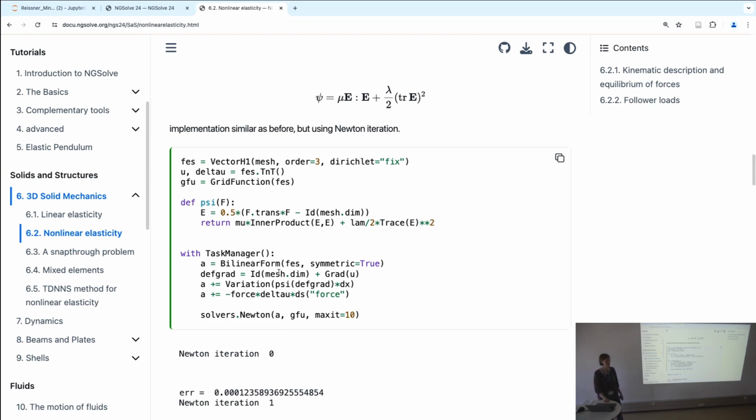So we use the virtual work formulation. We have now a different representation of the free energy function where we have the nonlinear equations. And here you could put in whatever nonlinear free energy function you want. It's not necessary to be a Saint Venant-Kirchhoff material. You can put, I don't know, Neo-Hookean, Ogden. No, Ogden is difficult. Ogden is not good. Mooney-Rivlin, Yeoh. Ogden is not good because you have eigenvalues, and differentiating by eigenvalues is not so great. Not a good idea.